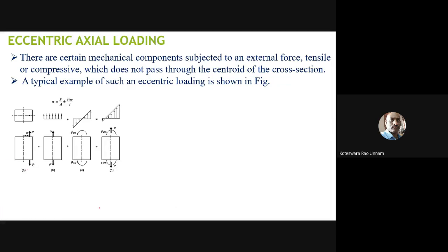So now, to find out the stresses when a component is subjected to eccentric loading, how can we find the stress values? First, we don't have a direct formula for computing stress when the load is an eccentric loading. So what we have to do is convert it into a load acting at the centroid. Here the load is not acting at the centroid, so we'll convert this to a load acting at the centroid. To do that, we need to use the principles of mechanics again.